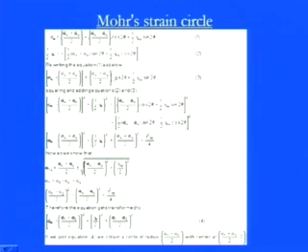So, we have (epsilon x minus epsilon y)/2 into cos of 2 theta plus half gamma xy sine of 2 theta, which is just a rearrangement of these terms. Now if I am adding both of the terms, equation 3 and equation 2, by squaring, then what I have is the component epsilon theta minus (epsilon x plus epsilon y)/2, whole square, plus the left part of equation 2, that is (gamma theta by 2) whole square. So, this square is equal to, now this is the term.